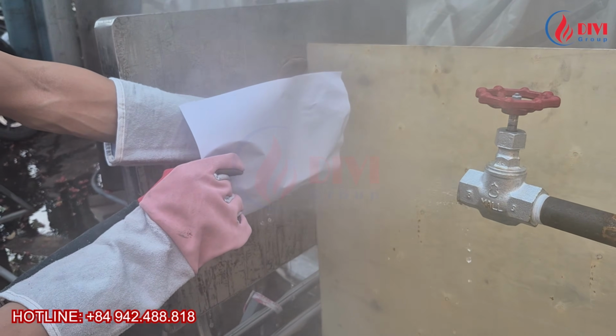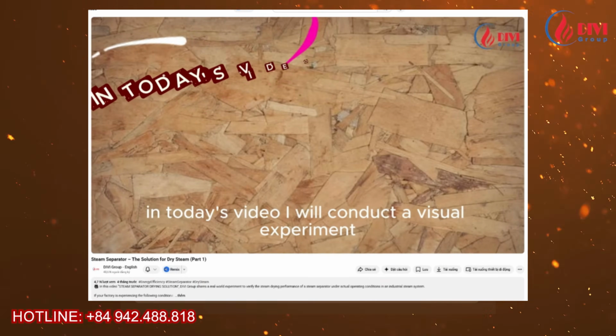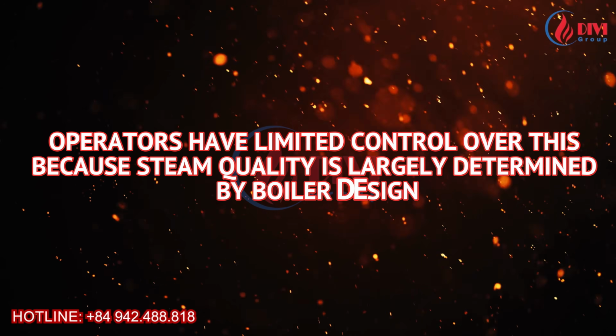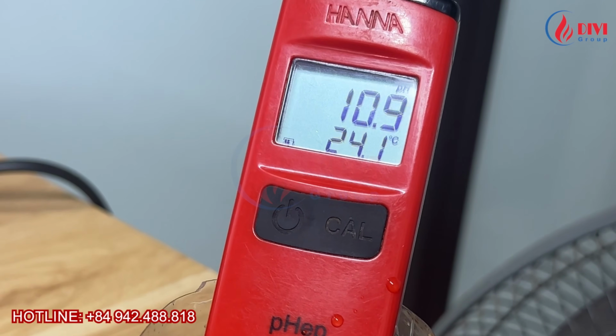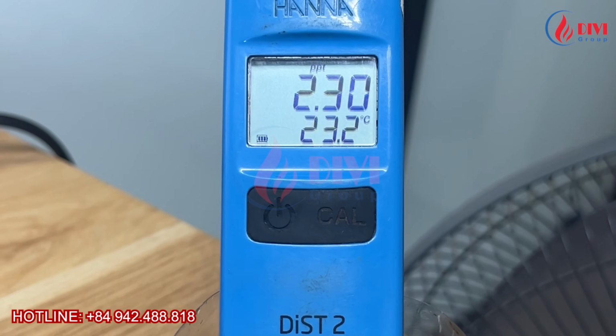This is what we refer to as wet steam, a topic I have discussed in several videos on the DIVI channel. You can watch our videos about wet steam and steam separators for a deeper understanding. In most cases, operators have limited control over this because steam quality is largely determined by boiler design. However, one important factor to consider is excessive chemical dosing, which can also contribute to wet steam. Many boiler treatment chemicals are alkaline and can create a soap-like film on the water surface. Overdosing may cause foaming and priming, allowing water to be carried over into the steam. Therefore, maintaining proper chemical dosage and keeping parameters such as pH and TDS within the recommended range is extremely important.